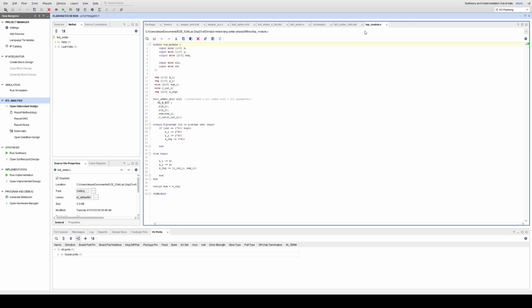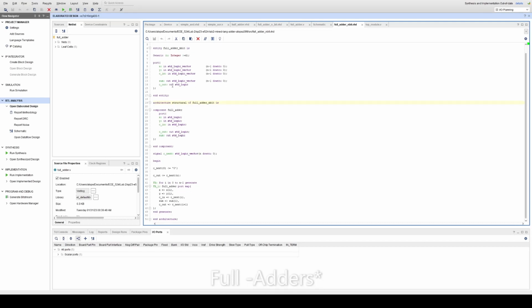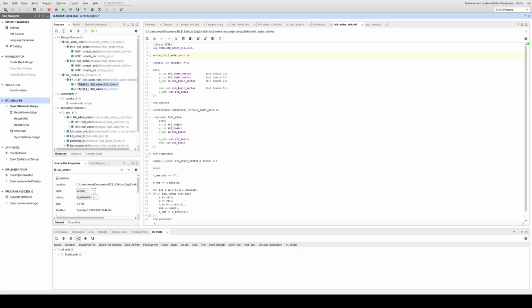So enough with that. Let's move on to the chain full adder with multiple half adders, as you will, or the n-bit adder. Some people even call it the chain adder, but this type of adder is for large binary numbers that can be constructed by cascading multiple full adders.